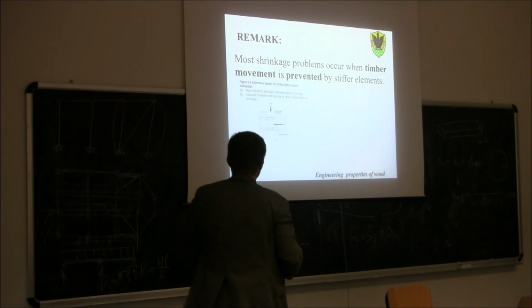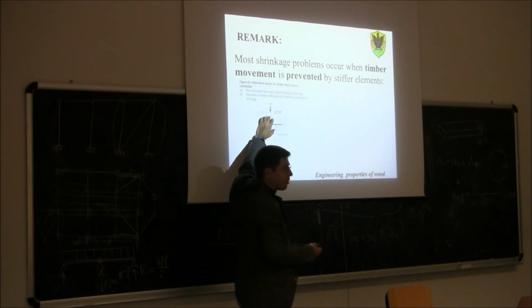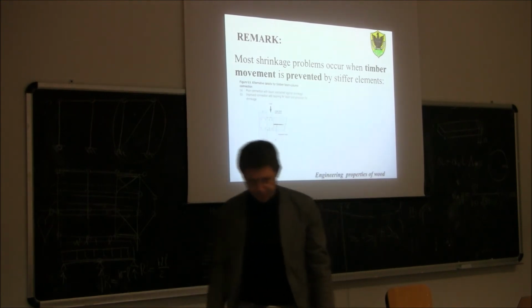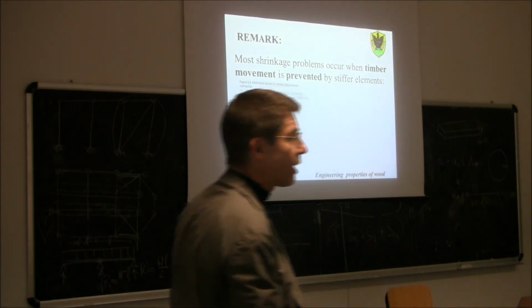So those bolts will basically keep this distance between the timber fibers constant over time. Now what is going to happen is this, for example, timber here is going to dry. So when we place the timber beam, it is at, let's say, 18% moisture content, and then the moisture content starts decreasing to 12%. What is going to happen then?